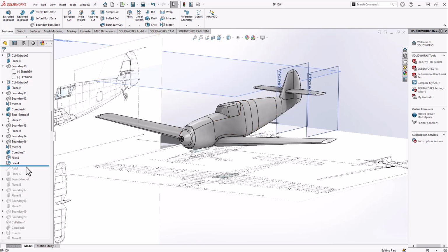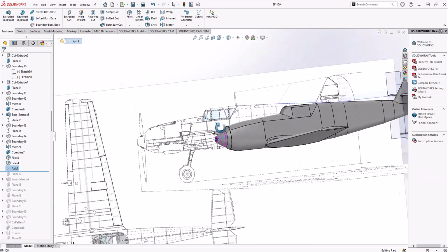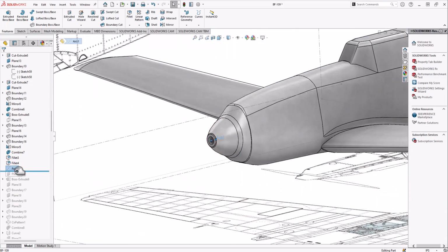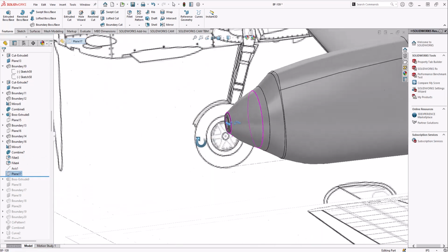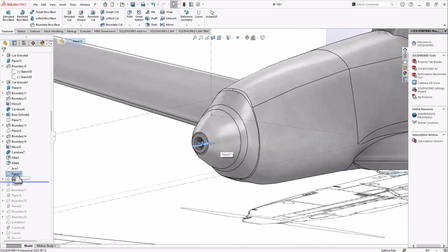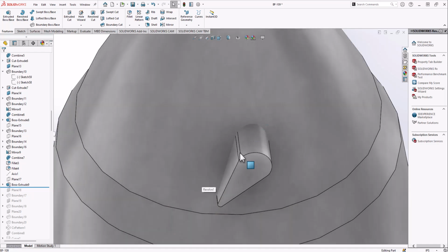And then for the propeller, that's the next step, and that's where I'm going to leave it. I'm going to finish the propeller, and then I'm going to end this video, and I'll probably add a timeline or something. So this axis is the symmetry axis of the propeller. I create a plane which is on that symmetry axis and perpendicular to the right plane. And then I just extrude a portion of the propeller blade, so it's got that airfoil design again.